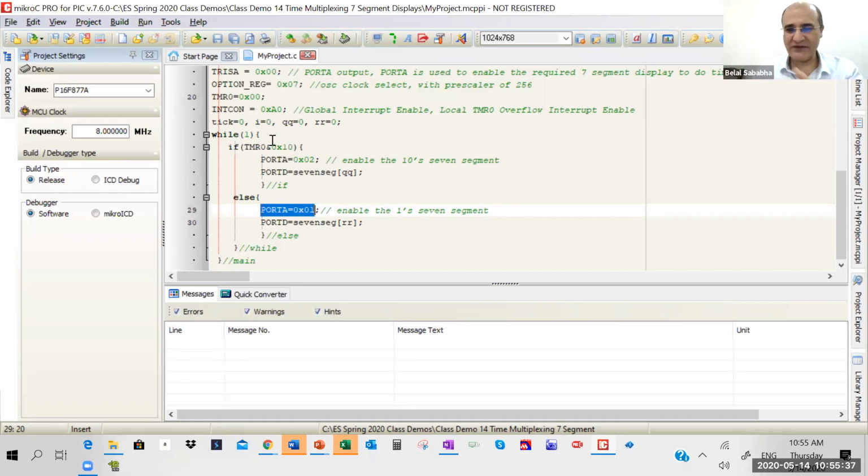Bit 0 in timer 0 flips between 0 and 1 every 128 microseconds. Bit number 1 flips every 256 microseconds, any slower, half the time. Bit number 3, half of that time. Bit number 4, half of that time.